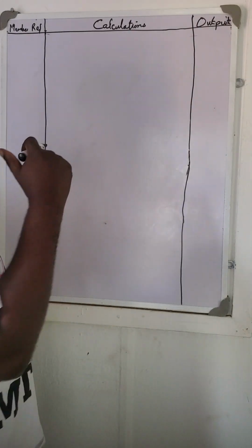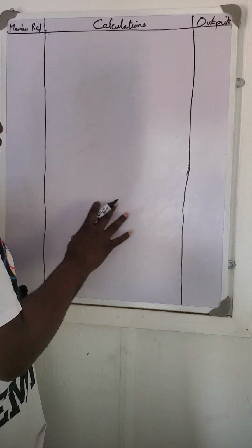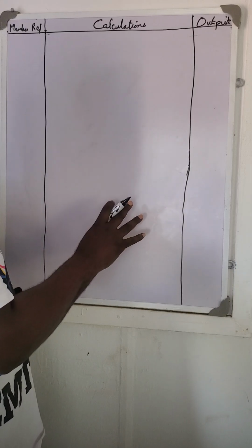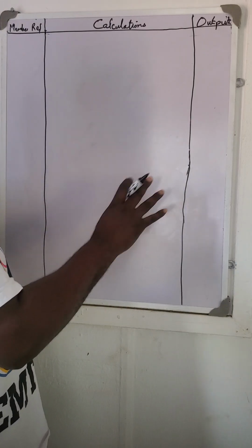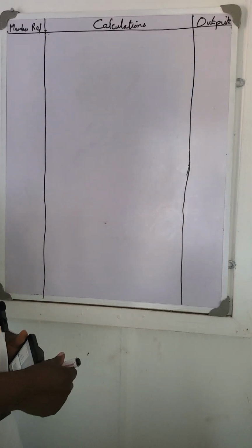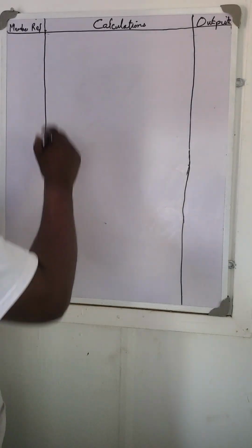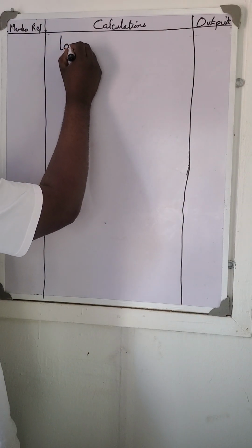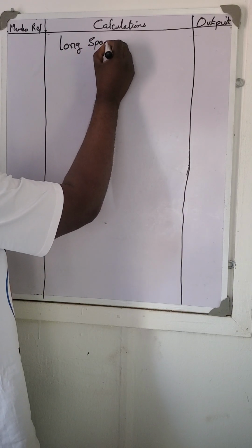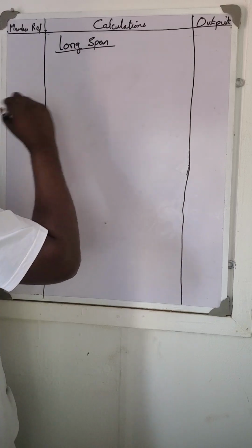Today we are going to continue from where we stopped. In our last class, we analyzed for the shorter span, then we provided the reinforcements. Today we are going to continue analyzing the long span of the same panel 1. That's the long span of that panel.